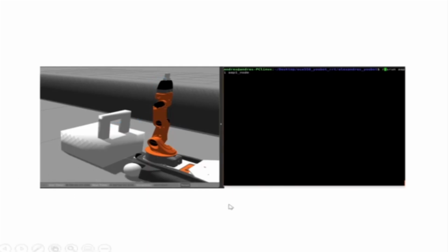Now in the next one, what we are seeing is, okay, the next video is basically for a serial arm manipulator. Now for the serial arm, it has to take the manipulator end effector and put it through there. So what it will do is it is trying to find configurations which are possible, which will take the end effector and put it through there using RRT only. Okay. So see as the video goes on, we see how it is finding.